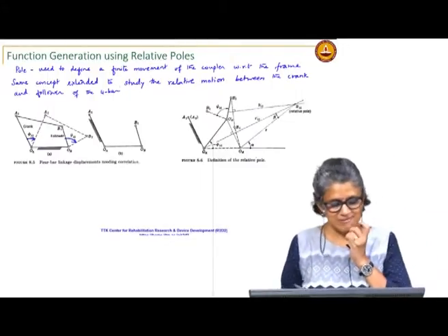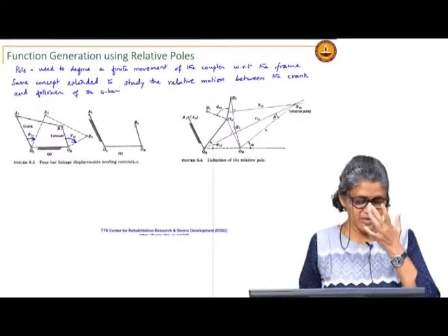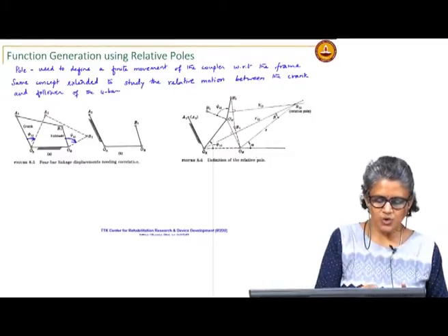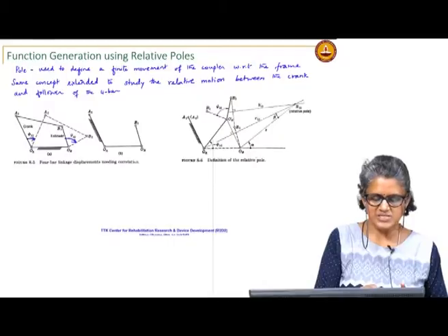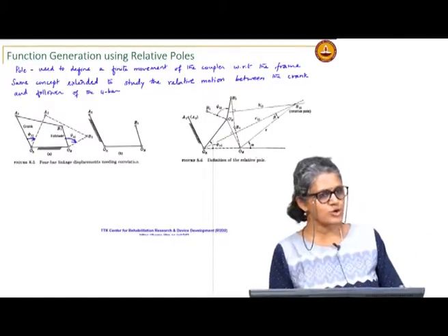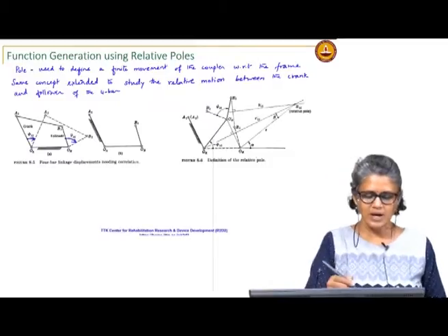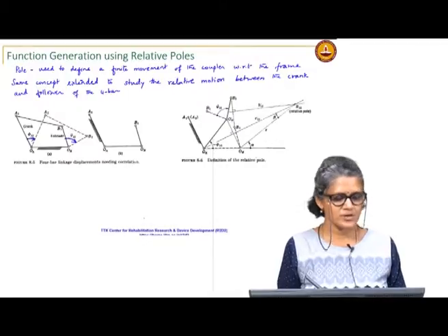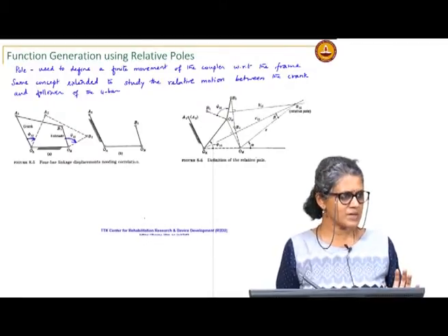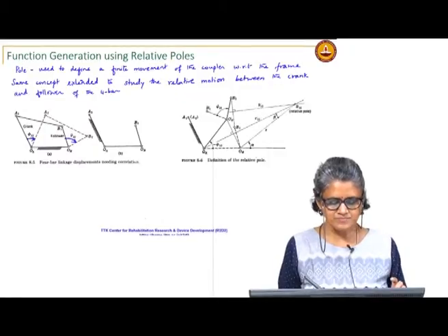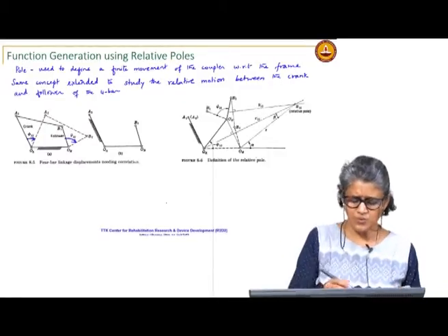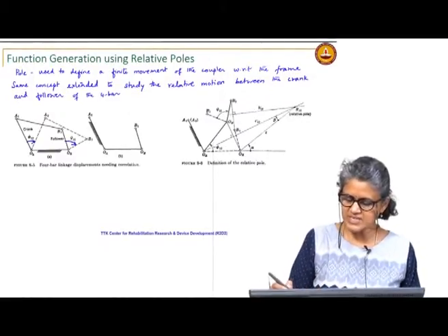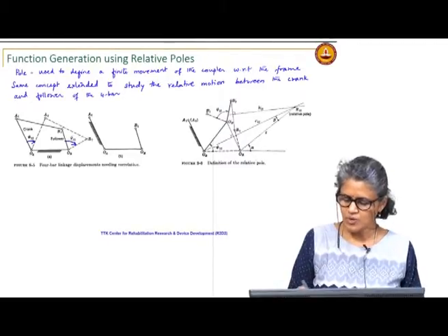So, let us first look at, again to understand this, we look at inversion. This is the 4 bar linkage you want, which correlates a crank displacement of phi 1 2 with a follower displacement of psi 1 2. Now, instead I make the crank the fixed link. So, I sit on the crank, OA A1 becomes my fixed link. And what did we do? By inversion, once I sit here, this OA OB B1,